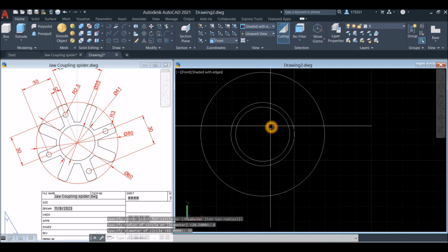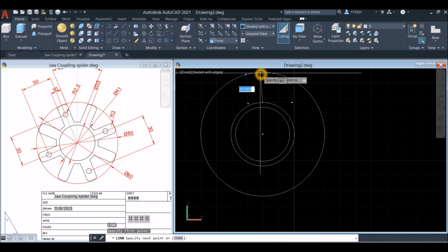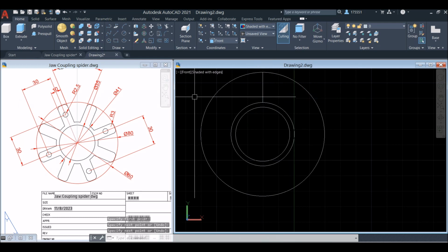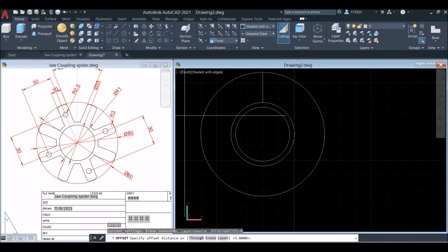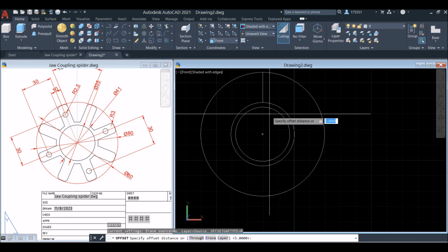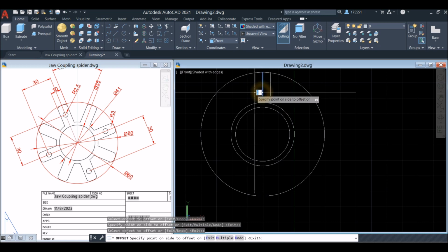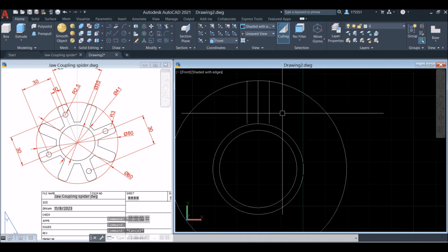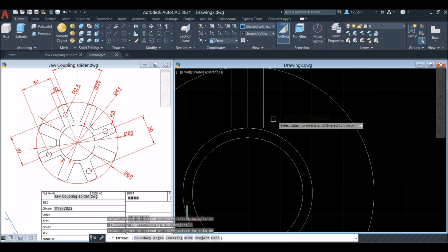Now I'm gonna draw a line as a guide from quadrant to quadrant. So this is what I'm gonna draw here for this leg. So offset command, O for offset and enter 5, which is half of 10. So it's gonna be between this point to this point. So 5, enter, click this line, click the side of this line and click this line. So what I'm gonna do is extend. So EX for extend command, enter twice and just click this one to touch that circle.